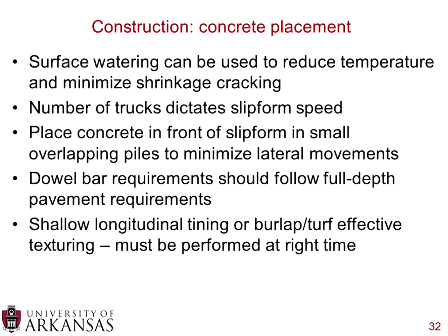Now, when you're actually constructing the concrete pavement, they do recommend that you use surface watering. This reduces the temperature of the pavement and it reduces shrinkage cracking. Again, you don't want to have a pond out there, but you do want to have that surface moist.